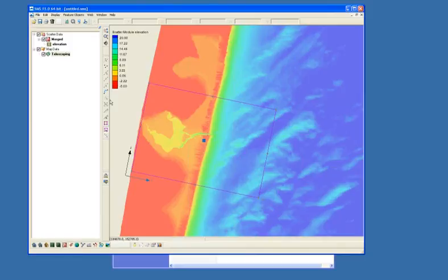So the difference between telescoping and variably spaced is the way the resolution is described. For the variably spaced grid, you resolve around a point, and for telescoping, you actually specify zones where you're going to have a certain type of resolution.